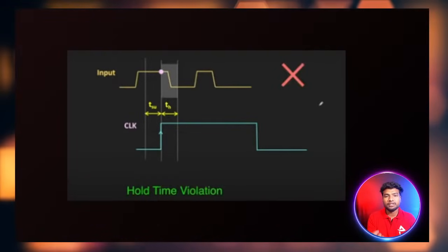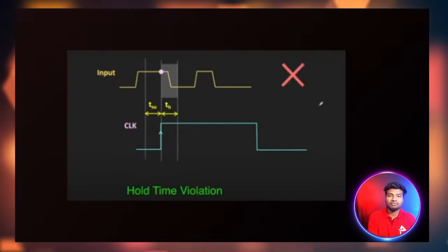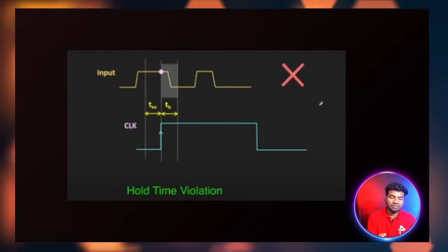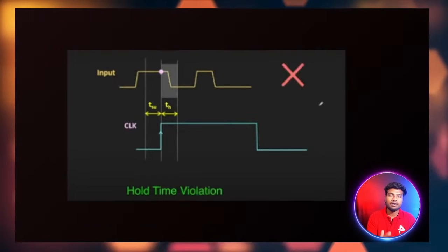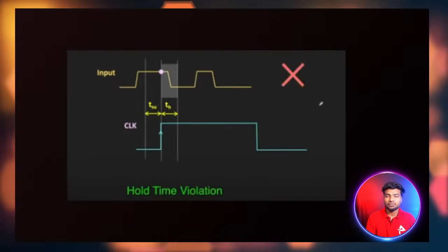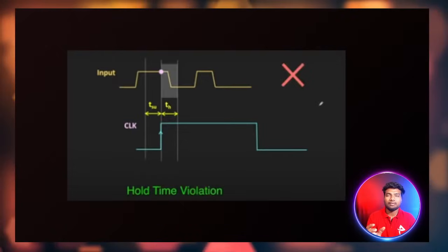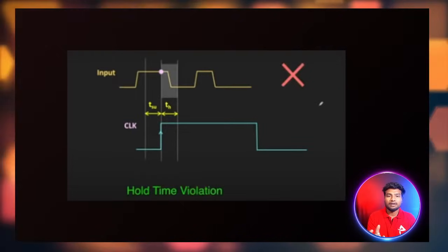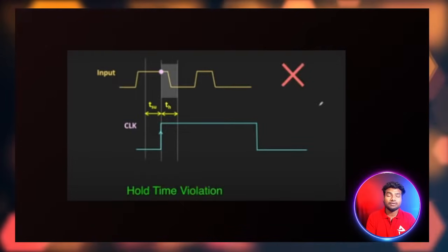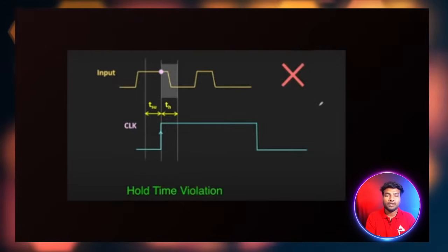Based on the frequency, you can know the time taken for one clock cycle. And then 50% means 50% is on time and 50% is off time. So you can easily find the duty cycle of the clock. How many nanoseconds it will take to make one clock cycle.